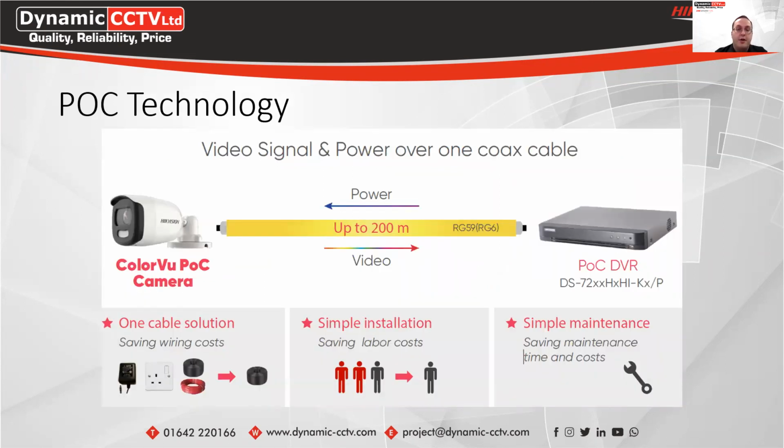So this will work at up to 200 meters on a single run of coax between the actual POC DVR and the ColorVu POC camera. So you've only got one cable going to the camera, and it gives you the benefits of POC in terms of saving time installing, as well as giving you the benefits of the ColorVu performance for your nighttime images within the system as well.